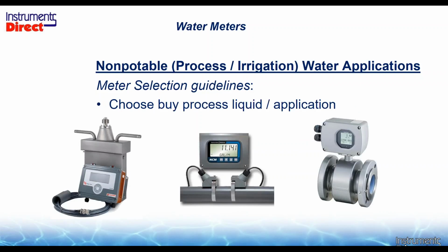And now we get more into the process side. As I said, we've got different flavors of the process liquid, solid content, temperature, pressure, and what is our net result. On the process side, we need to select the technology that meets the overall application requirements, but another thing thrown into the mix is accuracies. So depending upon your application, you can spend more or less for a particular flow meter based upon its accuracy performance there.